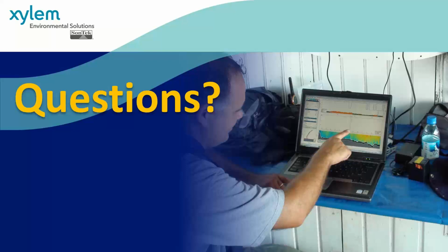So the best thing to try is just stick it in the water and see what you get. It might surprise you the ranges of sediment load that you can measure in. It definitely is very dependent on the concentration and the type, because round sand grains, the acoustics travel through without too much problem, but platy silt and clay particles are very efficient at blocking the acoustic signal.